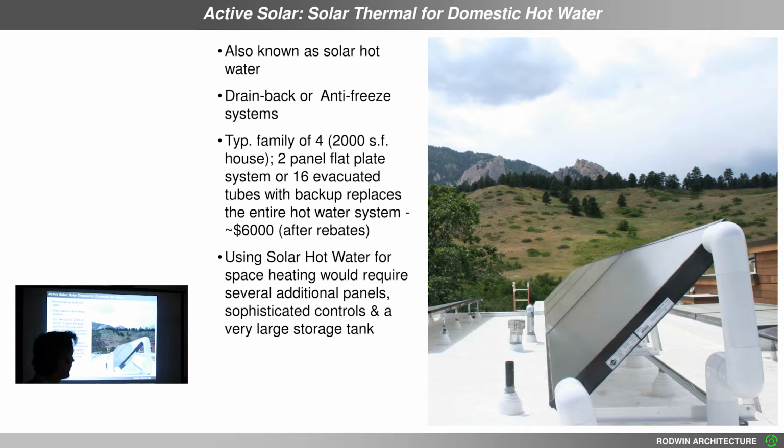Solar thermal, on the other hand, you are pumping water or liquid medium up to the roof onto essentially, there are two different kinds. One is a black plate like this, the other are round tubes. But you're pumping it into a chamber, sun is heating it up, and then you're taking that solar thermal energy and bringing it back down into the house and then transmitting it to the rest of the house to warm up the house or heat up domestic water.